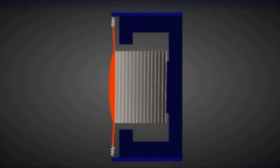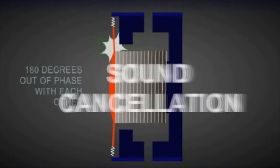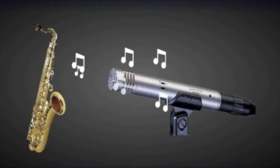In order to make a microphone directional, perforations are made in the housing near the diaphragm. The perforations allow sound from the rear of the microphone to enter the housing and strike the diaphragm. While this is happening, that same sound from the rear also travels around to the front of the microphone, where it also strikes the diaphragm. The same wave striking the diaphragm from opposite directions, 180 degrees out of phase with each other, causes cancellation, and hence we have a microphone that only hears from the front.